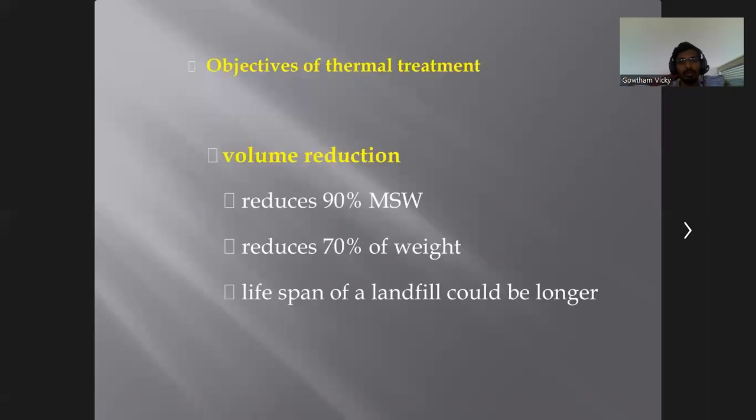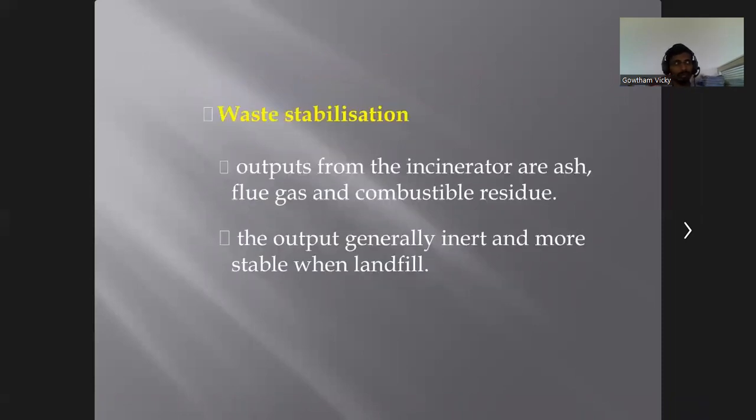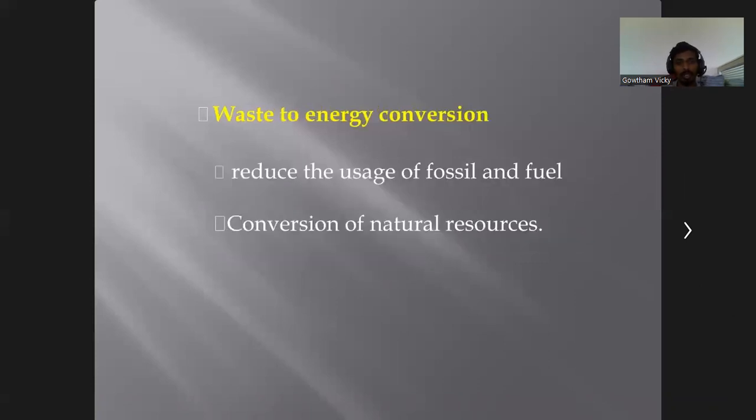The objectives of thermal treatment are, first, volume reduction. MSW should be reduced by 90% in volume and 70% in weight, and the lifespan of the landfill could be longer. Then waste stabilization: the outputs from incineration are ash, flue gas and non-combustible residues. The output is generally inert and more stable when landfilled. So these are the waste stabilization processes. Then waste to energy conversion, to reduce the usage of oils and fuels and the conversion of natural resources.